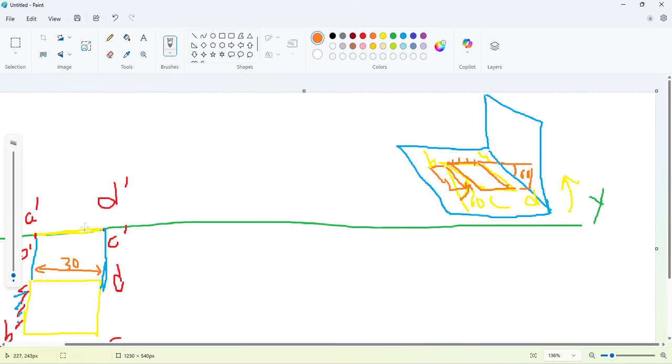So here, for the second step, in which this rectangular surface while resting on HP makes an angle of 60 degree, how to do this? Again, we have to just copy this from here to here. In the system, we can just directly select this and copy it from here to here, or in manual drawing, you can just measure this length. Suppose this is 30 mm.